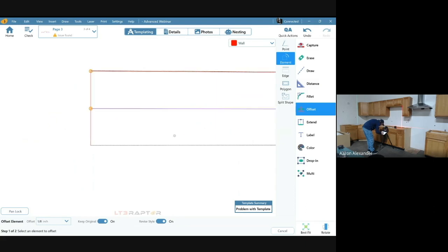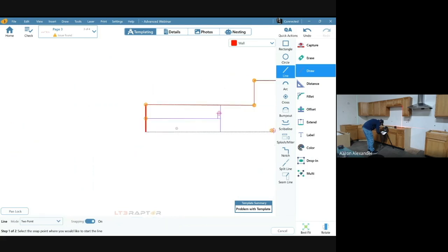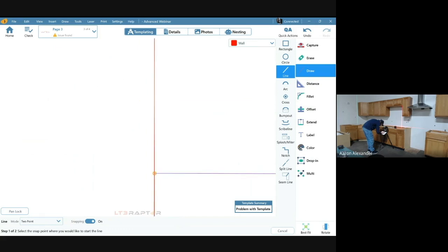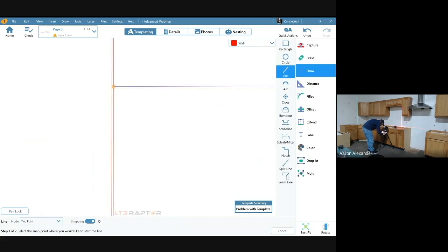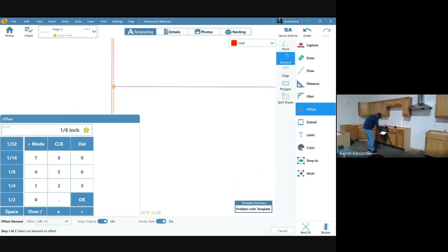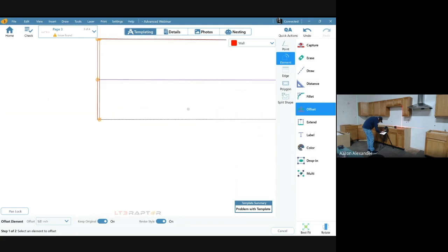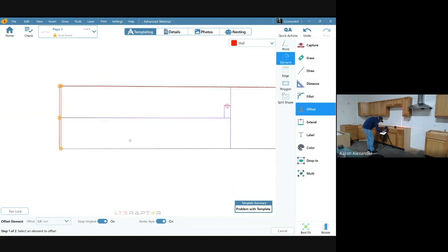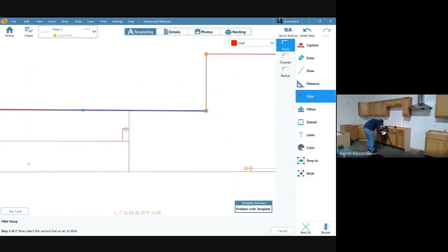And then down here on this wall, you might want to straighten that thing out with a 2-point line. And then we'll take that straight line and we'll offset that in. Like I was saying, if we're going to butt joint this, we could do that a 1/2 inch and it wouldn't matter, right? And then the bottom edge, we could just change that to wall for a rough cut. Then we can come in, fillet all our inside edges together.